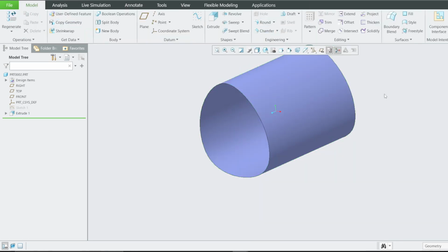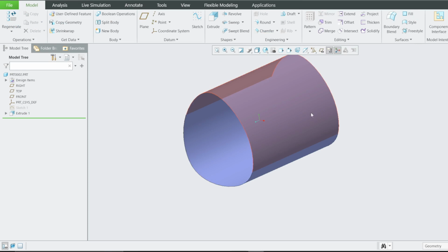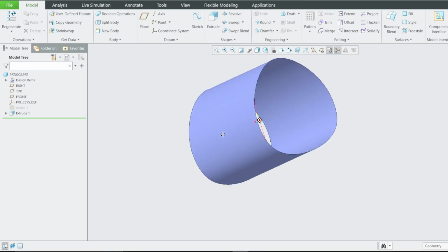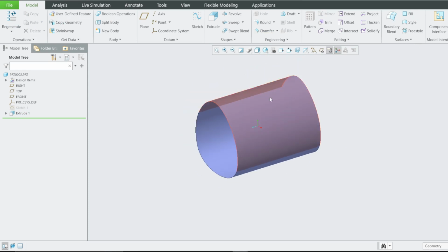That's the first body, the top surface body. For the surface modeling technique, you have to use what we call the subtractive method, whereby you create the main body, then start subtracting the other sections. Therefore, next we need to apply draft to this.